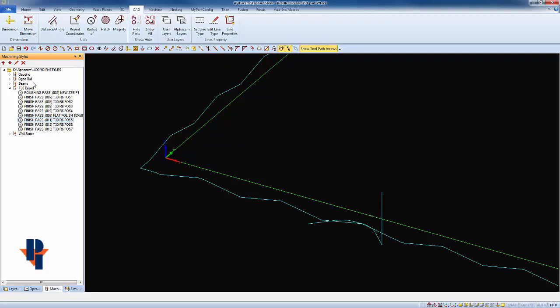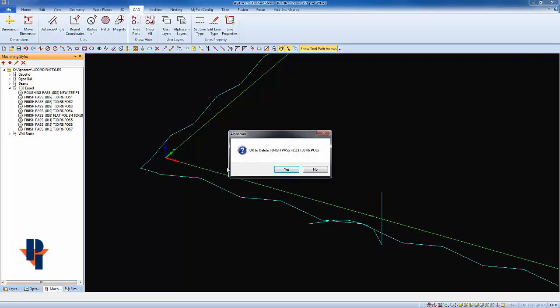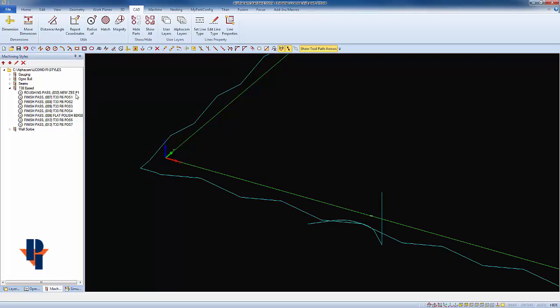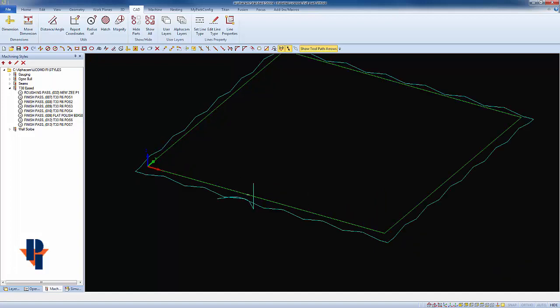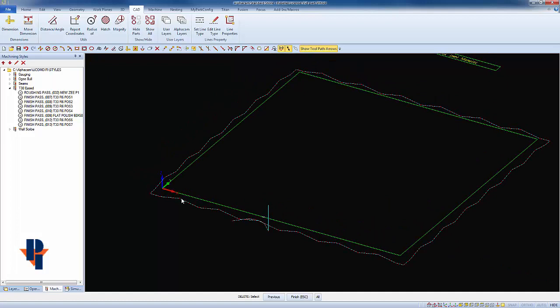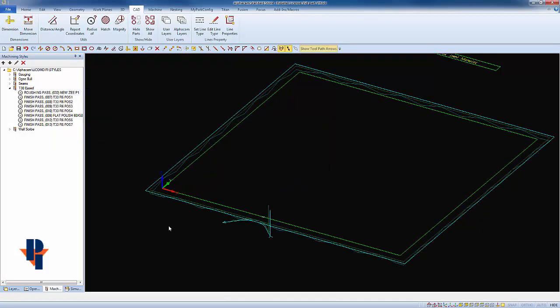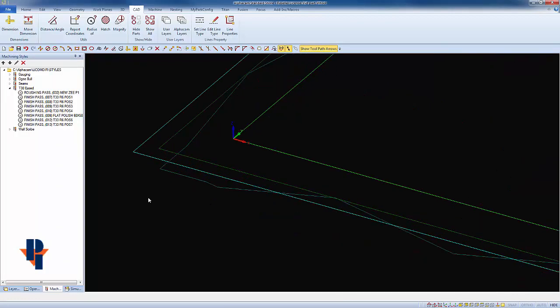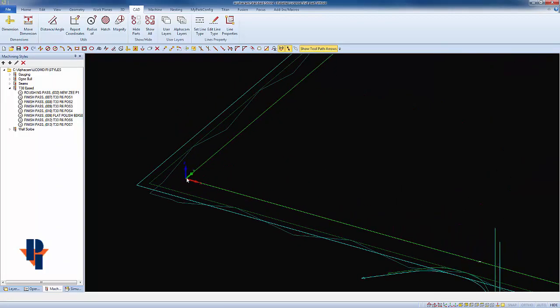so I'll highlight that one and delete it. So my tools now are a Z-wheel, position 1 through 4, my polisher, and then 6 and 7. Now to get a visual to see what we've done, I'm going to delete off this tool path, and I'm going to use this style and apply it as I normally would. And here we can see from here on out I have one tool within the style that oscillates.